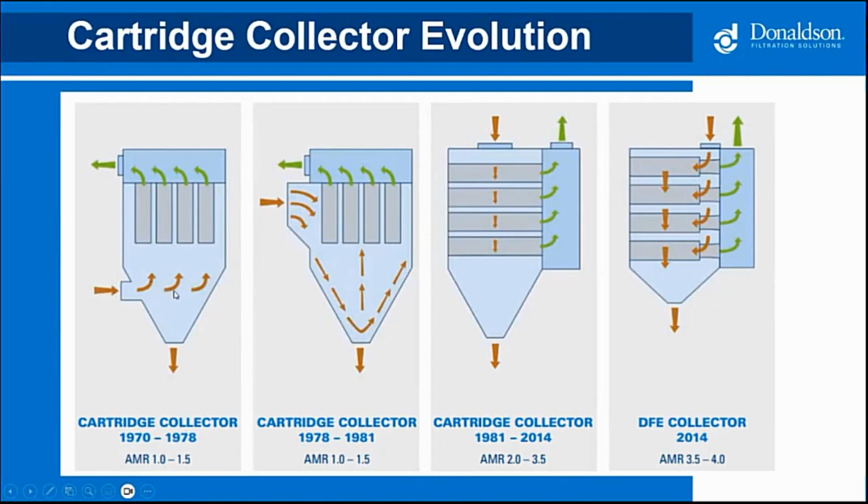Okay? So the air comes in low, it turns up. We also have to calculate a certain can velocity with this design, because as we reverse pulse, we want the dust to fall. The airstream on light dust is going to want to try to re-entrain. So therefore, this continuous duty collector just became intermittent duty because I need to shut it off and do a downtime clean.